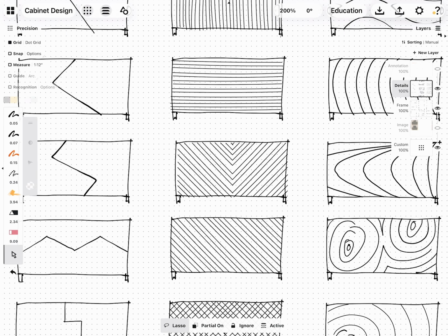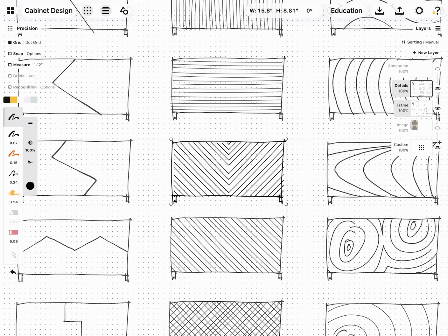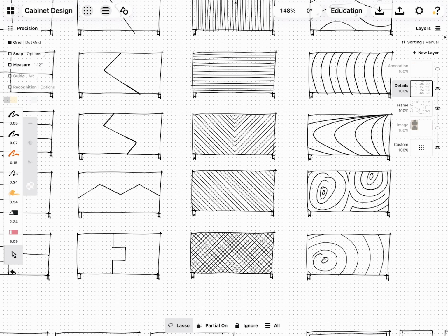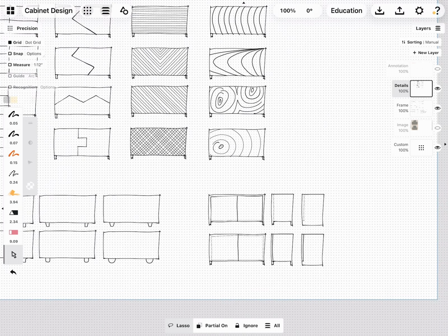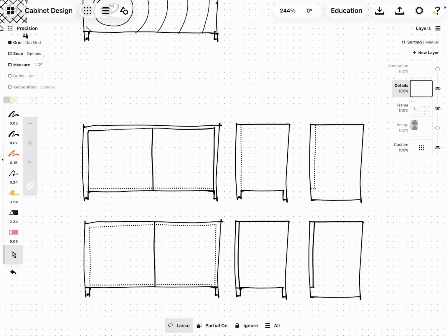And then if we want to adjust everything, we just select all layers. With my finger, I select all that, and here, that piece was a little bit to the right side. Sketches are quite nice, they're always good to use. Let me go to here. Also, you see I have a little bit more detail. So this is the setting for all the outline sketches, 0.07 inch for this document, a little bit of smoothing. And then for interior lines, so hidden lines, I'm using the dotted tool.